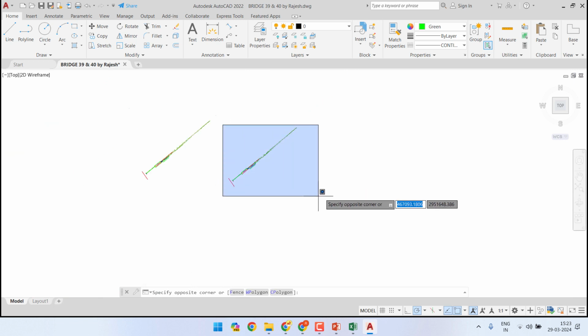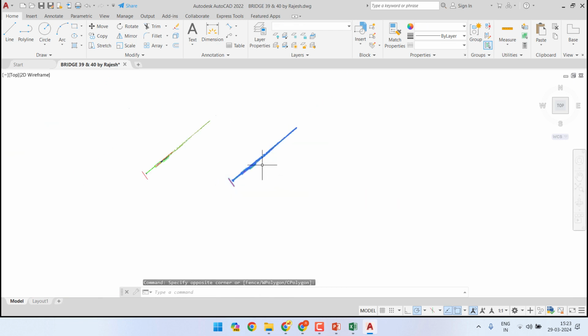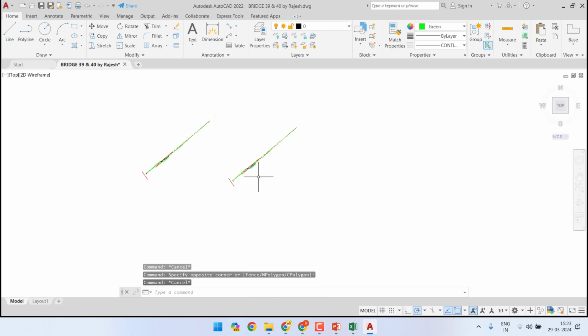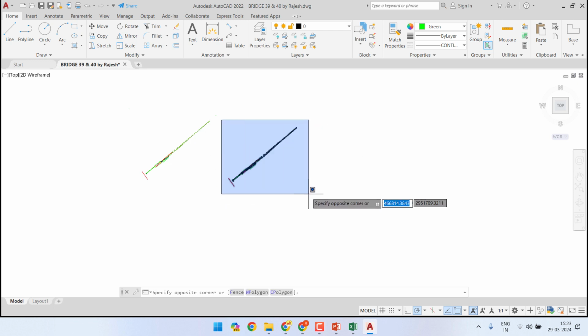I will also use a third criteria where I will use the transition length as 70 meters, because if we get the transition length as 70 meters, we can draw this reverse curve for sectional speed of 160 kmph against the 110 kmph that we currently have. So this is also an important part of analysis.